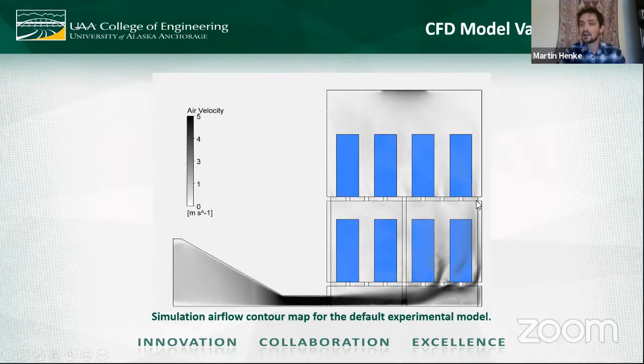And this, again, is one of the primary advantages of CFD, it would be very difficult to see this otherwise. So again, these batteries in the back of the enclosure are seeing a lot more airflow versus the batteries in the front of the enclosure. And again, this is leading to temperature differentials, which are extremely bad for the health of batteries in the line.